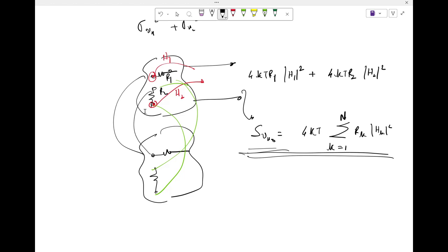Now if somebody tells you that they have a circuit which gives excellent noise performance, extremely low noise, the first thing you need to ask is, how much power have you burned? Because say I have a circuit which gives you so much power spectral density, let's say maybe 10 nanovolt per square root hertz, I just picked a number. And somebody tells you they have 5 nanovolt per square root hertz. When I say square root hertz, I mean I took a square root of the power spectral density.